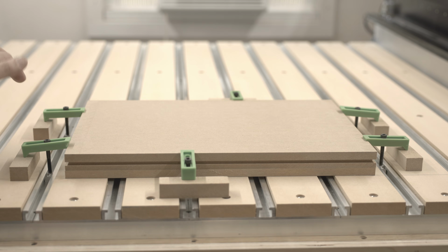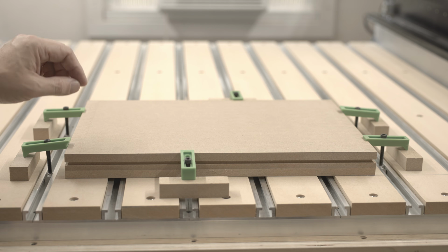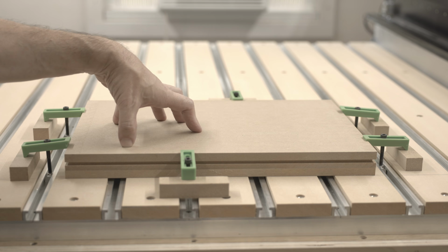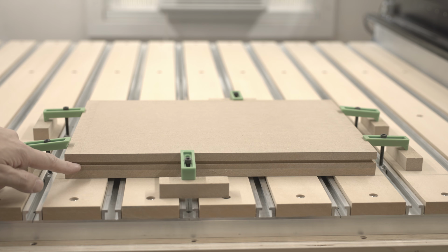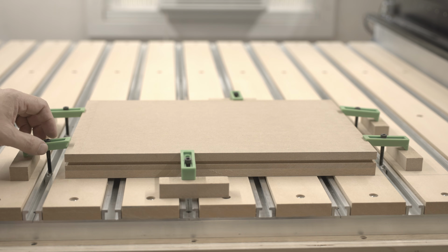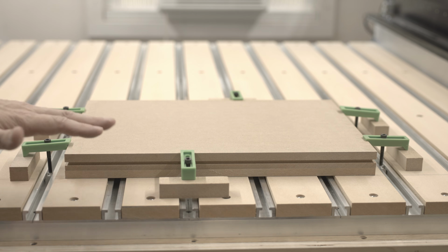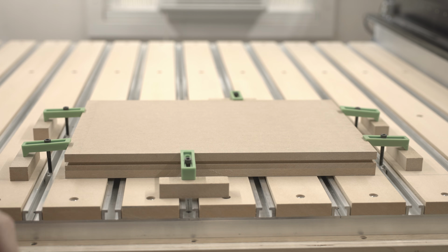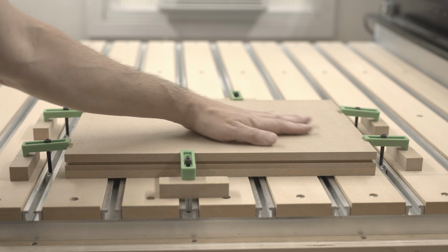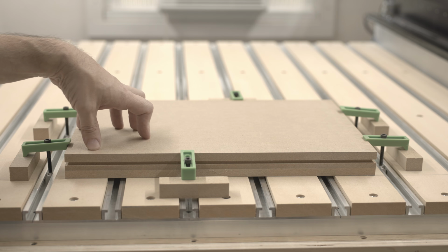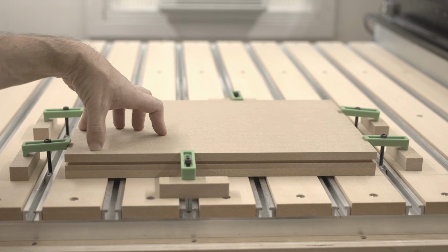I'm also using a system where the maple board that I'm going to be carving on has the same kind of groove cut into it like this, so that I can grab it from the side with these clamps, so that the surface is unobstructed and I can cut the entire surface without hitting a clamp or anything like that. All right, so I just wanted to make sure that that's clear. This is a very, very important step. All right, let's get to carving.